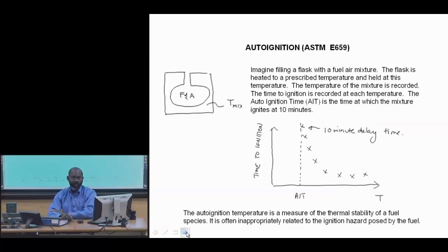So if you look for ignition or ignition classification of hydrocarbon systems in reference books or online, one of the things that you'll find quickly is that there is American Society of Testing Materials standard ASTM E659, and what that test does is it classifies liquids, hydrocarbon systems, others, in terms of something called an autoignition temperature. I'm not a big fan of the use of the autoignition temperature for practical problems because I think that it gives the wrong message to people.